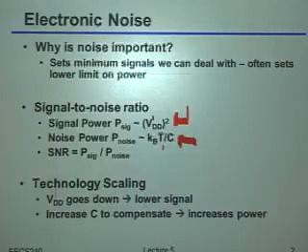If I want to quadruple my precision, I add 2 bits. Big deal. I went from 10 bits to 12 bits, or 14 bits to 15 bits, or even 31 to 32. It doesn't really change much. In the analog domain, not so easy, because every single bit costs you quite a large amount of power.